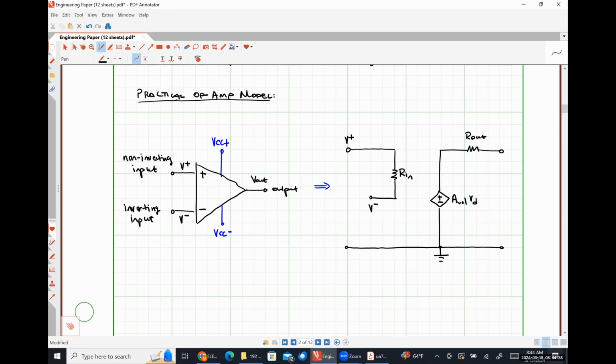So our differential voltage VD, we are going to define, and it will always be true, is just the potential difference between the voltages applied across our input resistance, where the positive polarity terminal of the differential voltage VD will always be on the non-inverting side of the amplifier, and the negative polarity terminal of the differential voltage VD will always be on the inverting input terminal side of the amplifier.